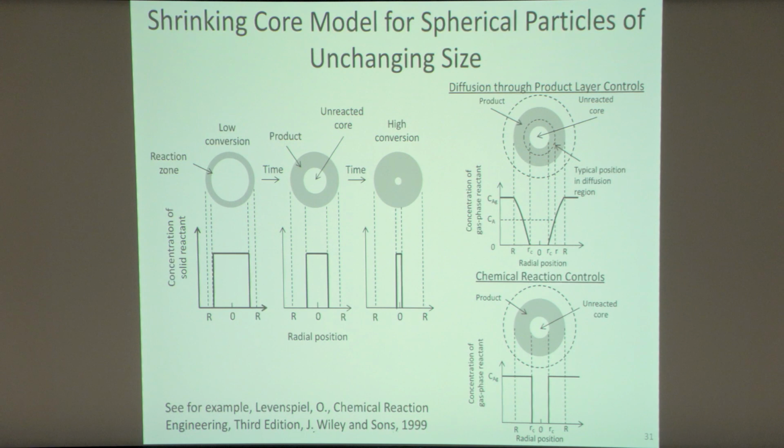So if I'm burning these particles in a combustion system where the temperature is only 2,500 Kelvin, then it's highly likely that the particles are going to be burning close to that temperature. And as a consequence, they're not going to be vaporizing, right? So all of a sudden, the nanoparticles, no matter what condition, I'm going to be burning them heterogeneously, independent of pressure.